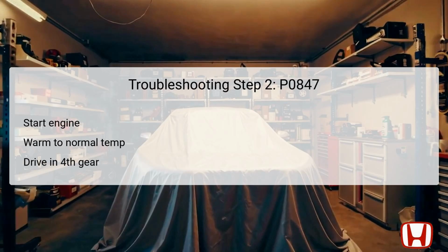At this stage, start the engine and allow it to reach the normal operating temperature, indicated by the activation of the radiator fan. It is important to drive the vehicle in the fourth gear for at least 2 seconds while having the shift lever in the D position, as this step helps complete the diagnostic cycle necessary for the HDS.